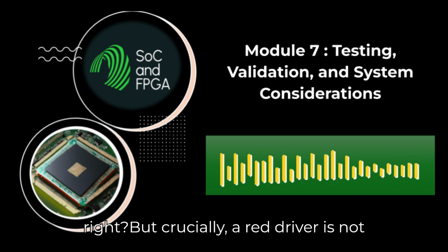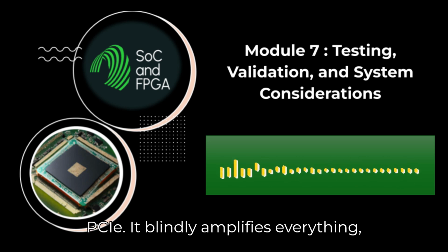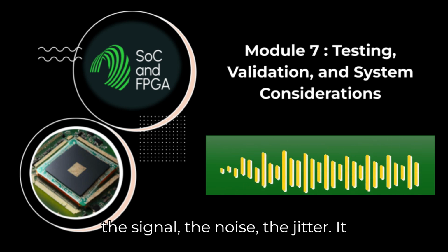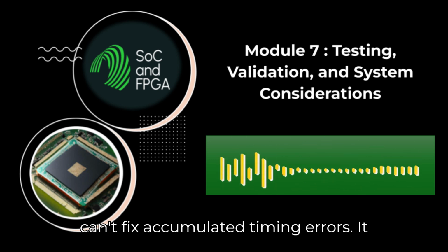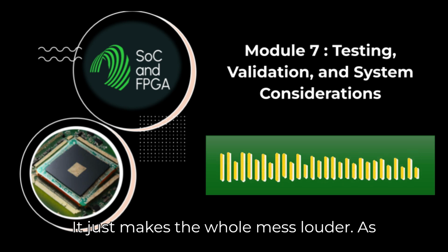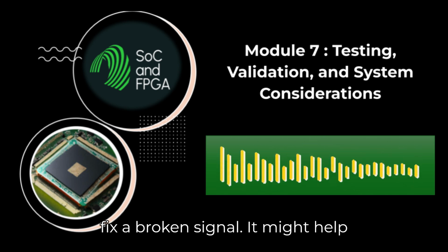Right. But crucially, a redriver is not protocol aware. It doesn't understand PCIe. It blindly amplifies everything, the signal, the noise, the jitter. It can't fix accumulated timing errors. It can't compensate for lane-to-lane skew. It just makes the whole mess louder. As the saying goes, a redriver cannot fix a broken signal.